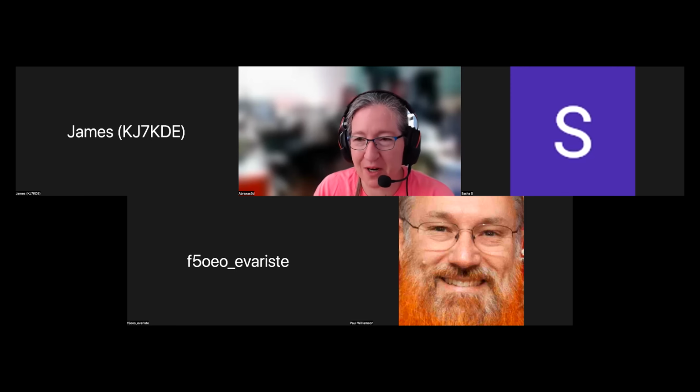Okay, let's try to figure that out. It seems that the initial sample rate is more than 100 megahertz. Yeah, we know that, 122. And so we can't have a DVB receiver which handles that, so we have to figure out how to change the sample rate.